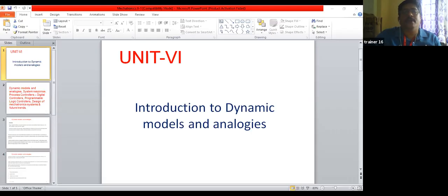Right. So here, whatever the motion converter, that is the transformation of the motion from one form to another form, maybe a linear to rotational, and the mechanical elements, that means linkages, cams, gears, rack and pinions, chain drives, belt drives, these are all we can replace. Then they have to be replaced by hydraulic and pneumatic actuation systems.